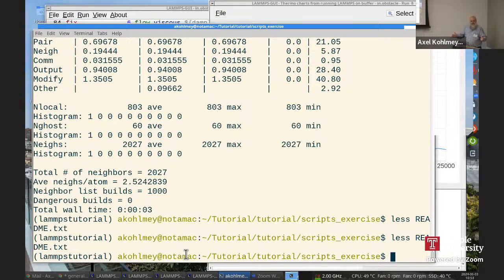And again, this of course works the same way for the command line as it works for the GUI. But you see with the GUI, a lot of the steps get easier. If I need to look up the manual, it's just one command. And you also see once you know the hotkeys, it's very convenient to just go through this. So even though I don't usually need a beginner level introduction to LAMMPS, I use the GUI because for simple inputs it's just so much faster to debug stuff, because everything is within the same executable, and you can just run hotkeys to make a change, rerun.